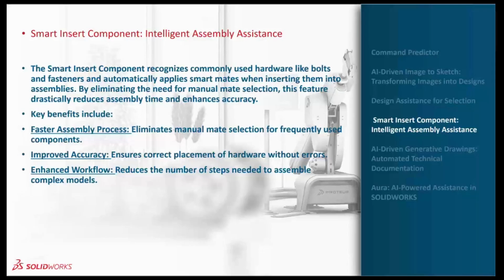With that option, by simply dragging and dropping any component, it automatically adds to that particular position. But from SolidWorks 2026 onwards, no need to do all these repeated works. This option is specially for the hardware library like bolts, nuts, washers. So hardware library components only. Irrespective of whether you created mate references or whether you use the same component in any other assembly or not, by simply dragging and dropping any bolt or any washer to that particular hole,